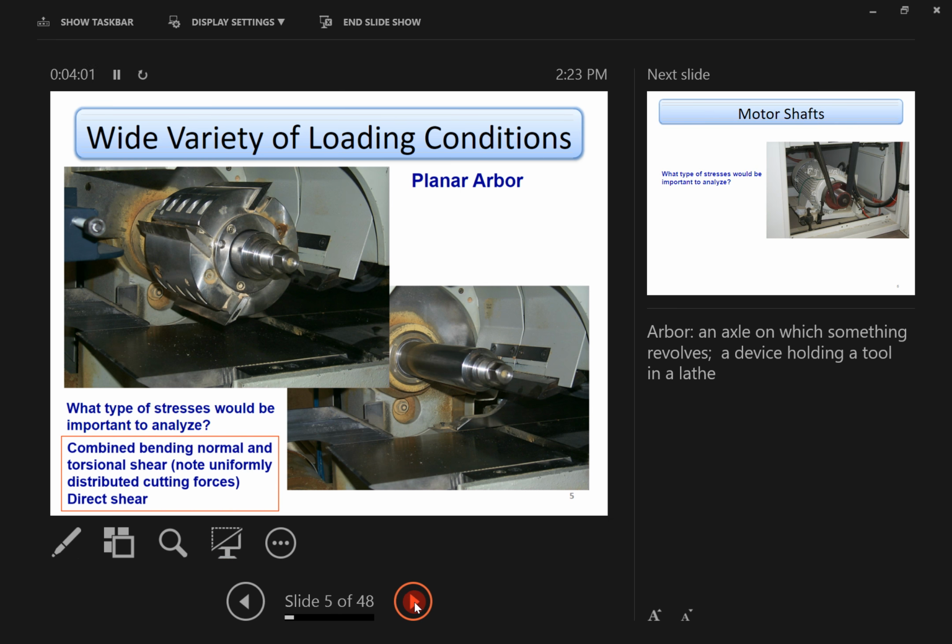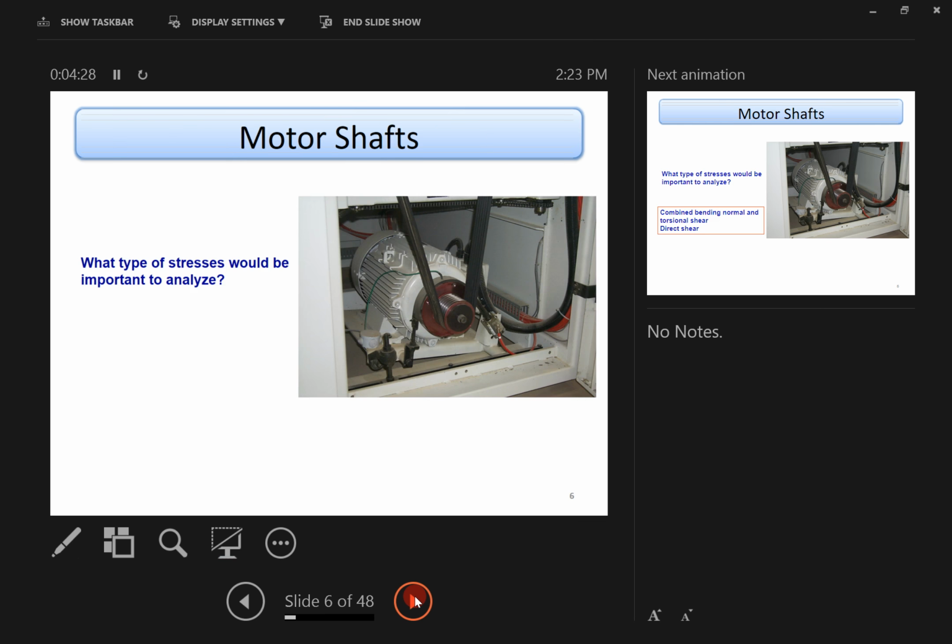Another thing that will come back later is that it's a fatigue loading, and we're going to have to be able to identify what type of fatigue loading. Fluctuating. If it's a fluctuating type of loading, what's the amplitude? What's the mean value? Whether there is a mean value or an amplitude, that's all up to the actual loading condition.